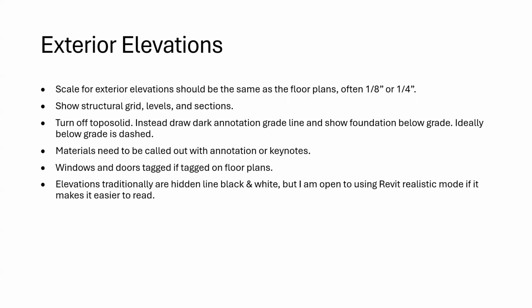So let's keep going here. Typically, these are the rules. The exterior elevation should be at the same scale as the floor plans. If you're working on a house and your floor plans are at 1/4 inch per foot, your elevations on your working drawing should also be at 1/4 inch per foot.